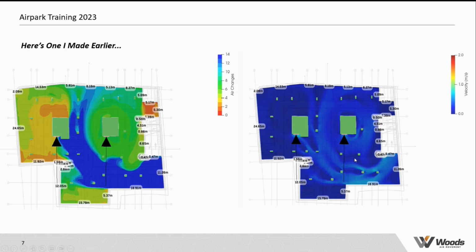Using this, we can see where the air is flowing within the car park and at what speed, allowing us to visualize the overall flow patterns within the car park and thus identify regions of recirculation which could cause pollution to be retained within the car park or lead to smoke logging in an emergency situation, leading to an overall reduction of performance as the pollutants are retained and recirculated around the car park into areas where it may not necessarily have been there before, and just generally retaining it and not being directed towards the extract and extracted from the system.